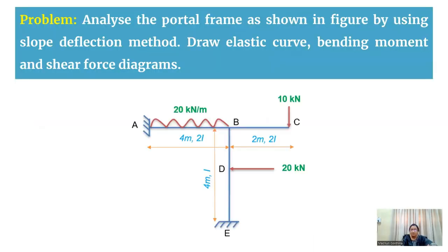Coming to the problem. So this is a portal frame that has been given. For this frame, we are going to analyze by using the slope deflection method. Finally, you're going to sketch all the figures, that is the elastic curve, bending moment, and shear force diagram.